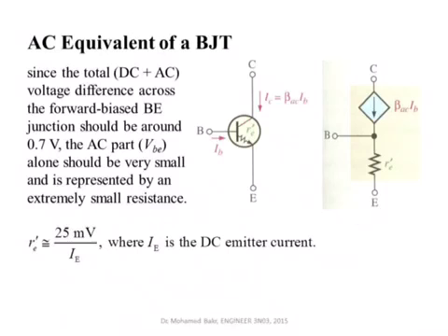Similar to the case with the MOS transistors, once we have determined the operating point, when we apply small changes in the base current, this will result in larger changes in the collector current by the value beta AC. As a result, if there is resistance connected to the collector or to the emitter, we get an amplification of the voltage changes at the base.